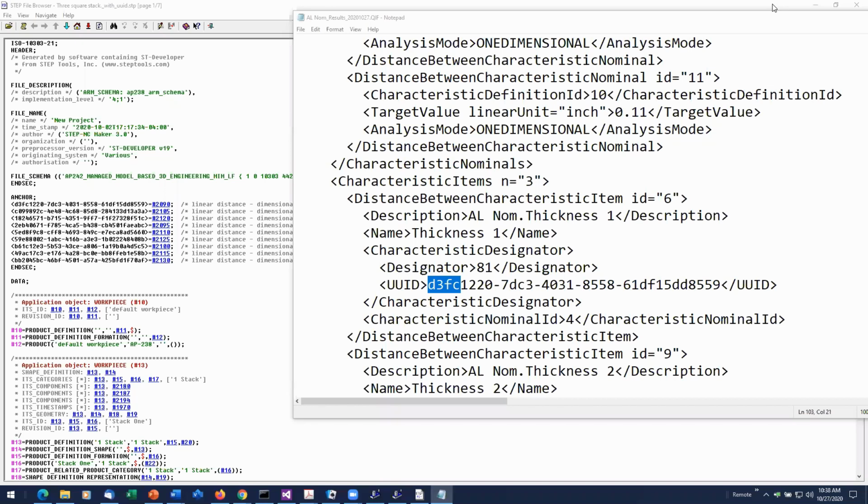I think it's a matter, Tom, of being smart about what it is that you're trying to achieve. In this particular case, when I'm thinking about drilling holes with a robot in my use case, drilling holes in the wing of an airplane, I care, for the most part, about keeping track of my condition of assembly. I'm caring whether that hole actually got drilled or not. On a robot itself, most likely I'm going to have an end effector that's actually going to drill the actual hole. So for the most part, I'm going to care just about whether that hole is there or not. That's the granularity that I have.